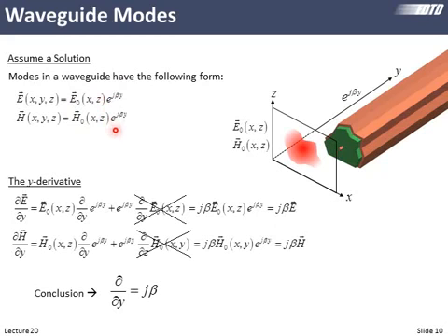So let's think about what happens now when we take derivatives in this y direction. Very little is changing. There's no materials that are changing. These amplitude terms, they're not a function of y, only this propagation term. So let's go ahead and take the derivative of the electric field. When we do that, we use the product rule, and we have the electric field times the derivative of our propagation term plus the propagation term times the derivative of the electric field. Well, remember the derivative in the y direction of this amplitude term is not a function of y, so this term completely crosses off and becomes 0. And of course we can real easily take the derivative of this complex exponential. So the moral is we take the derivative of E in the y direction, we get j beta times the amplitude term times e to the minus j beta y, which is just j beta times the original electric field.